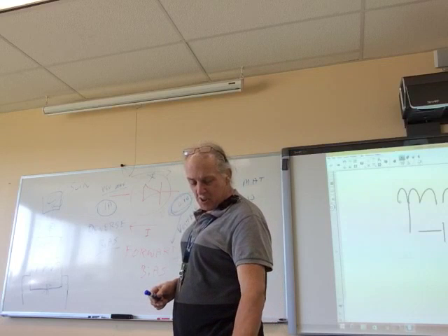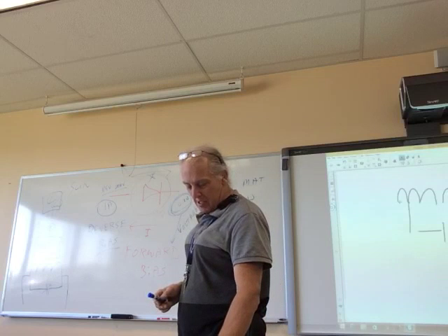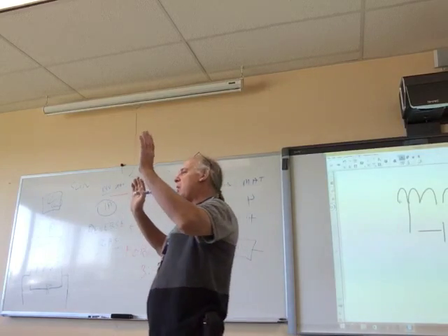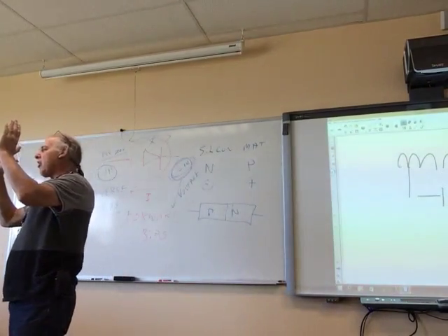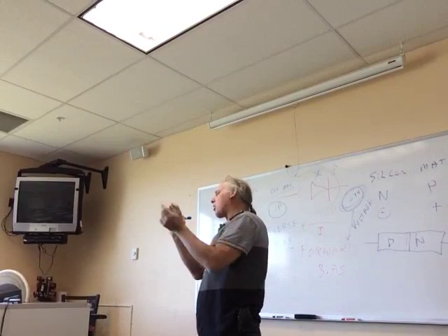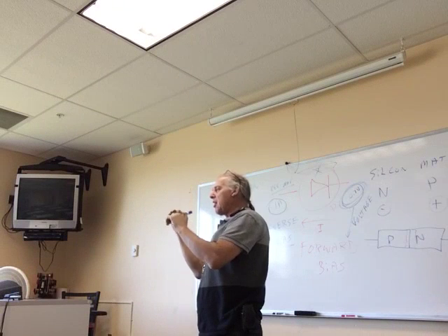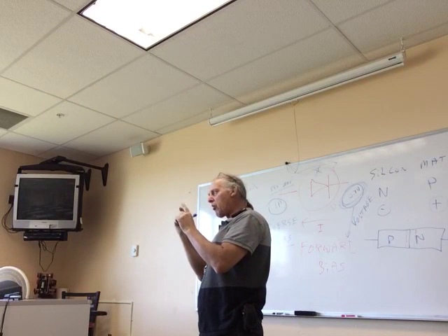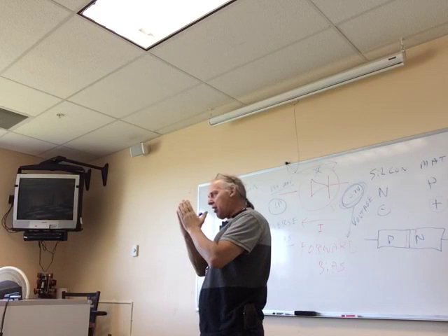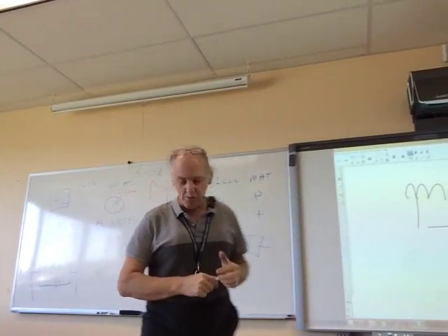Okay. On the next page, it actually proves that it's 0.7 volts at the depletion layer. That would be 210, okay? And it shows current flow, right? What happens to the depletion layer is as you get closer and closer to the 0.7, it gets narrower and narrower until finally the electrons can come across. And then it looks like a wire. No loss at all, okay? But as long as you're below that 0.7, no current flows. It's trying to build up enough electrons at the depletion layer and make it small enough so they can get across, okay? Depletion layers are important because it's going to happen with transistors too.